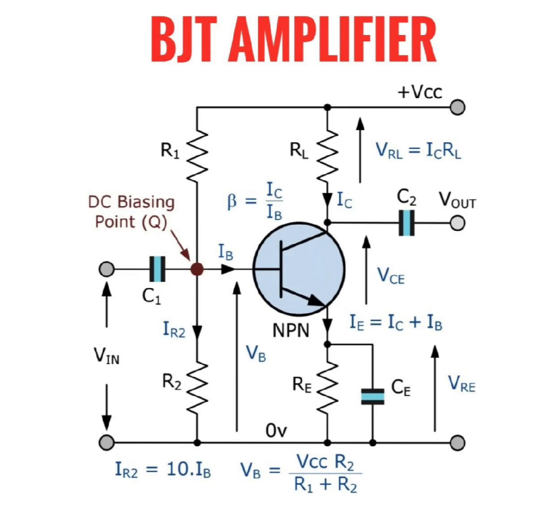Now we want to talk about forward bias and reverse bias. What does forward bias mean? It is when the PN junction is connected so that current can flow easily. In our transistor, the base-emitter junction must be forward biased, meaning the base-emitter voltage is usually 0.7 volt.